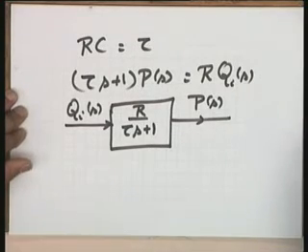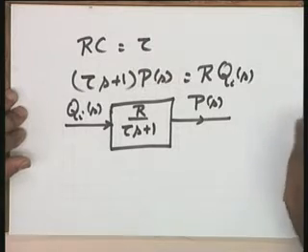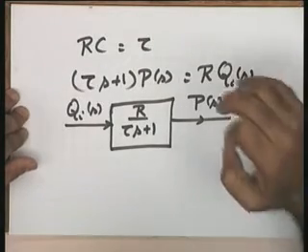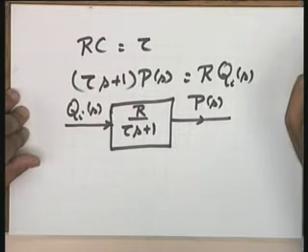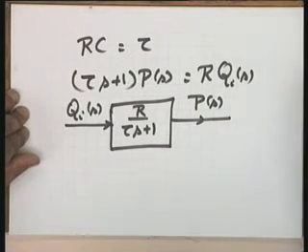Let me make a statement: the parameter equivalent to inductance has not been taken in our thermal models as well as liquid level models. Can you tell me the implication of that on the total modeling? The implication is that the models will turn out to be suitable cascades of first order models.